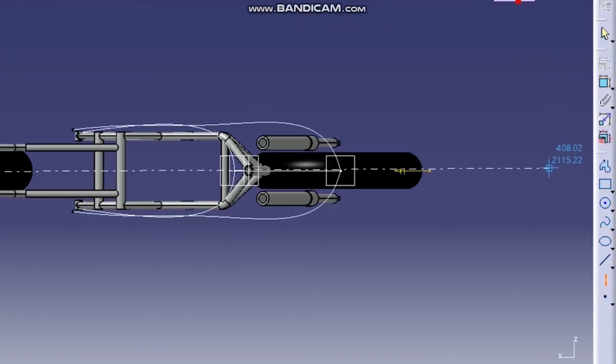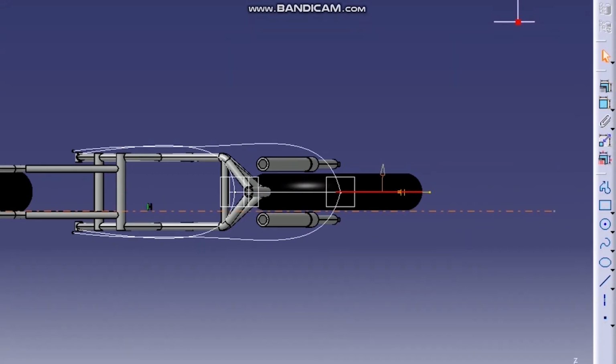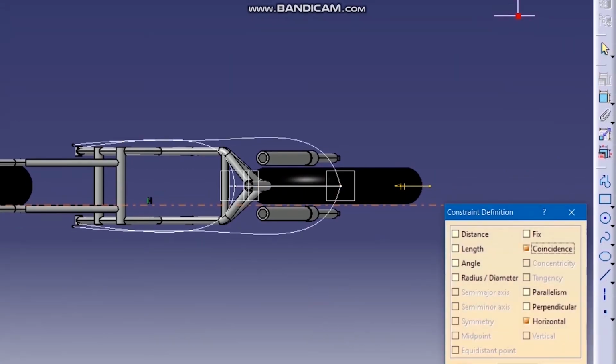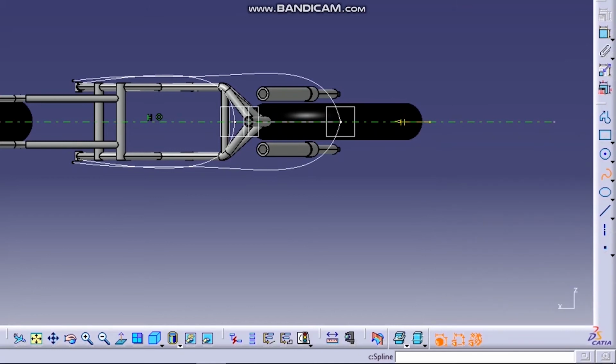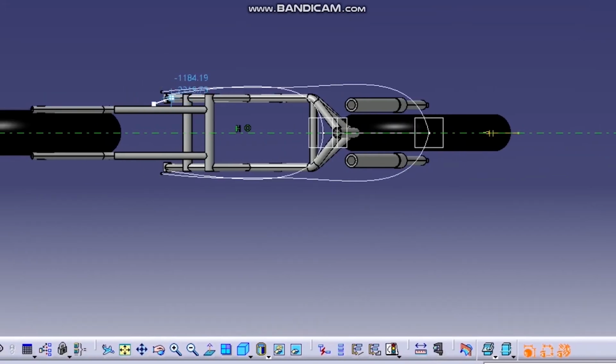So in general, the fairing will be converging towards the end. So try to make the bottom part as thin as possible, so the whole thing seems to be converged. Repeating the same thing again, chassis axis, and drawing a sketch using the symmetry.